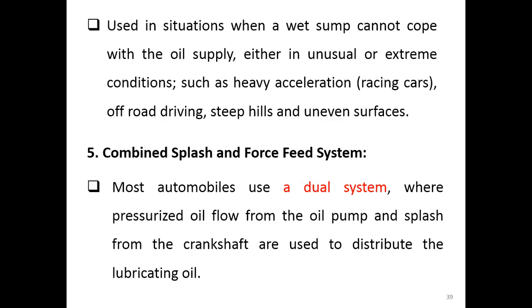And when you cannot maintain the level, that means you may not have lubrication oil, because the pump may not be able to draw the oil from the reservoir inside the engine. So that is the reason why, in this situation, the dry sump is preferred over the wet sump.